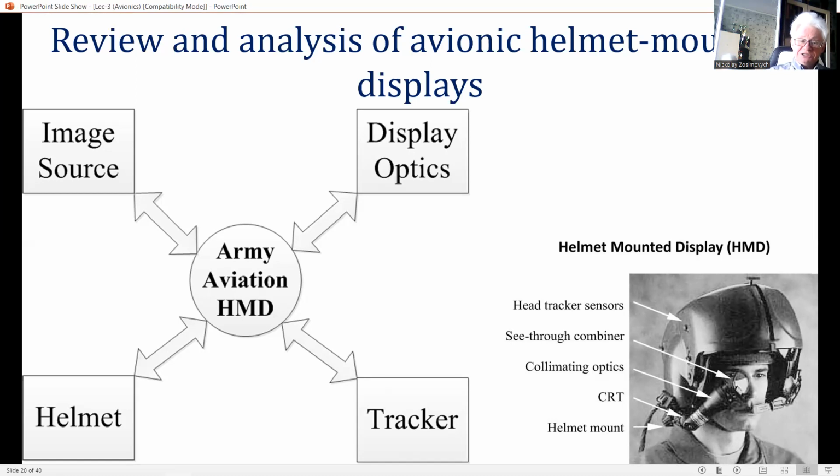And there is a large market for a low-cost, lightweight HMD for fighter aircraft, which are primarily involved in daytime operations, to provide helmet mounted cueing and a sighting system. The lower weight and the cost achievable with a visor projected monocular HMD can make this a cost-effective solution in such applications. Also configured for daytime use, such a system is capable of displaying video from a sensor, providing the pilot with an enhanced viewing system after dark or in bad weather.